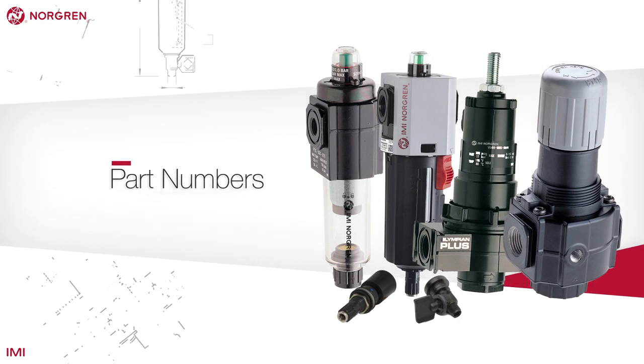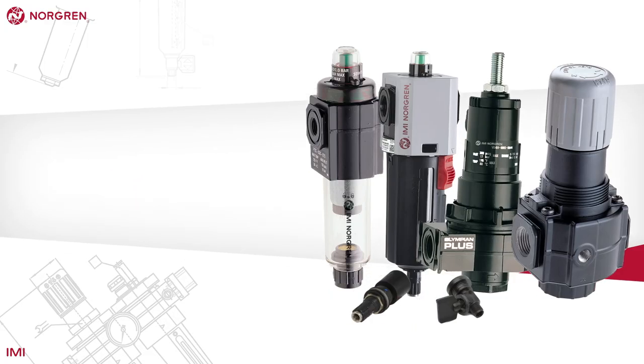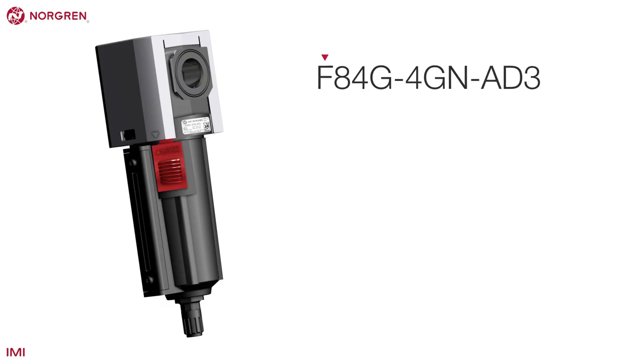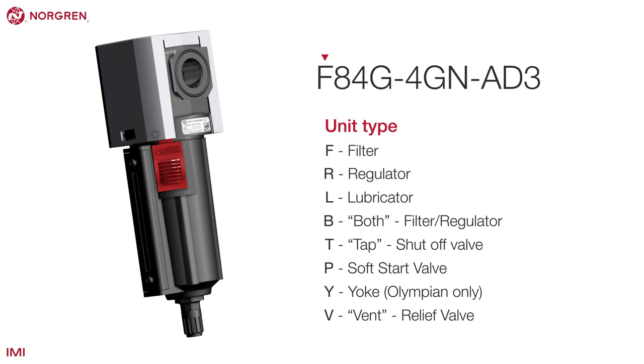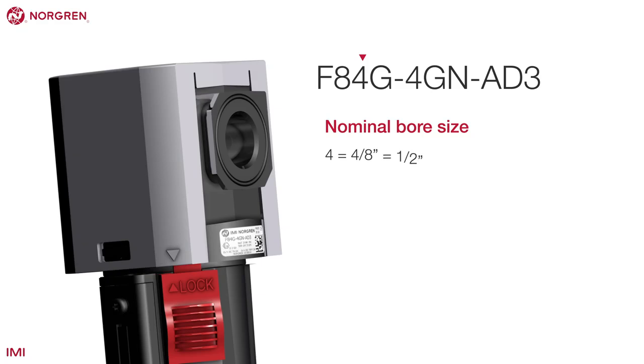Norgren has a formula for creating part numbers. This applies across the new range, but is especially relevant in air preparation products. Let's look at a part number. The first digit represents the type of unit, in this case, a filter. The second digit represents the product range, in this case, Excelon Plus. The third digit gives us the nominal bore size, which, as we mentioned, relates to flow. This is measured in 1/8 of an inch.